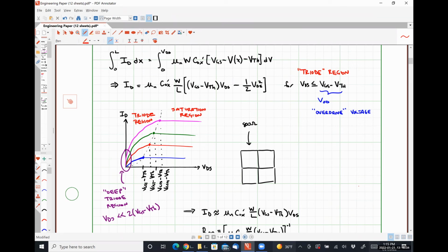So I would encourage you guys to try to wrap your head around these things and get an understanding of what saturation means for MOSFETs and what saturation means for BJT, so that you don't get the two of them confused, because that's obviously going to be a bit of an issue when we're working with these things. Okay. Cutoff region is effectively the same thing, means the device is off, so there's no difference there. Good for us.